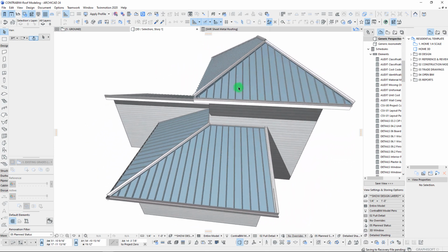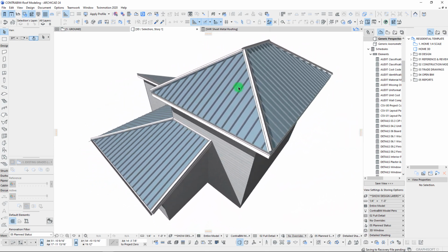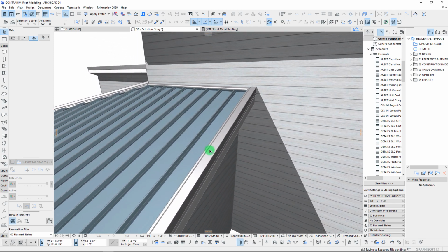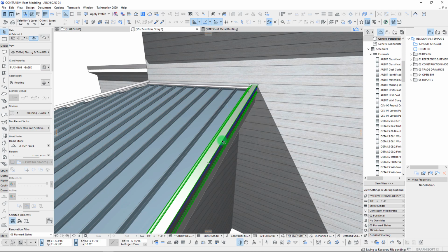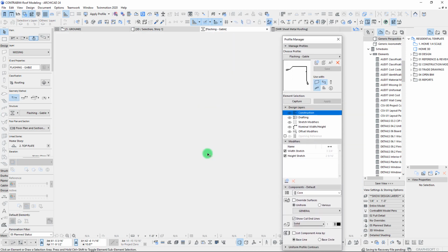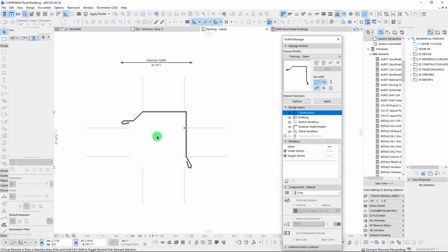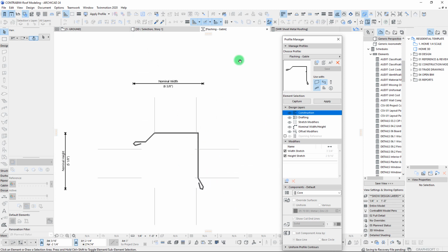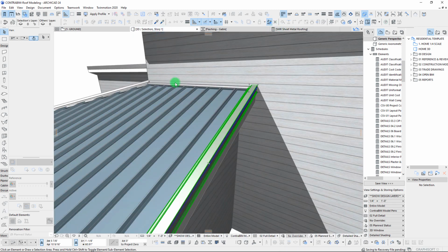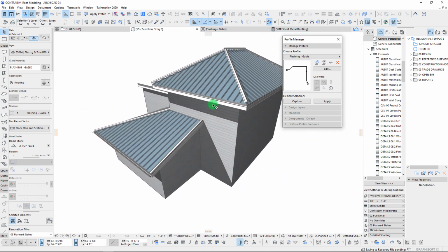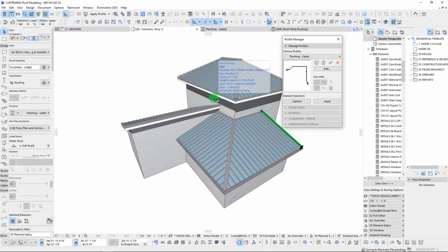Obviously, a lot of this is in going through and setting up the complex profiles. And what's nice about this is anytime you want to modify a profile, you can simply start making adjustments here. And there are endless options for creating different details and different flares for your specific sheet metal flashing. So, all right, I'll wrap this one up here.